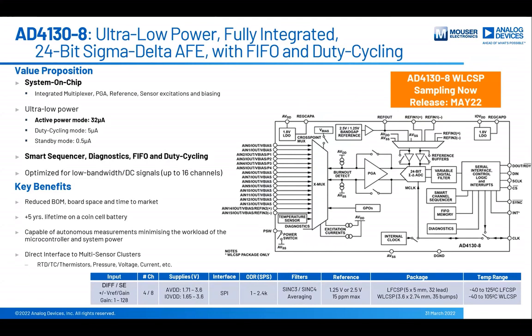Taking a look at the block diagram of this device on the right-hand side, you will see that it is truly rich in features. Not only does it take care of the sensor biasing and excitation, which is important for some of the sensors that we just discussed, it really has various options available, from selectable excitation current to onboard precision reference voltages that are also selectable.